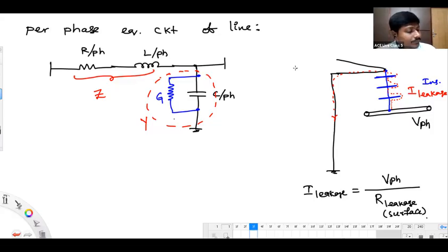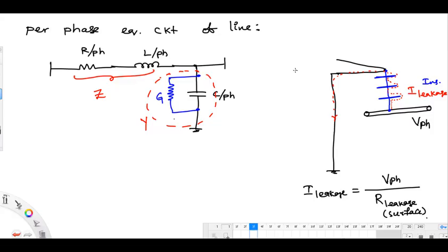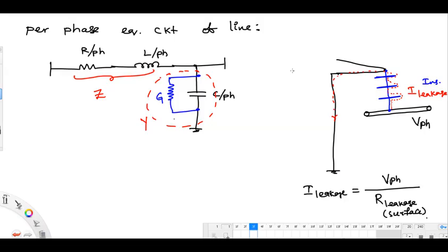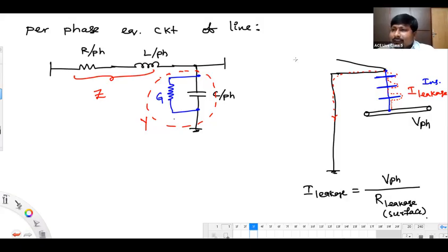One general doubt, sir. Four or five years back, we were using a 60-watt bulb. If we continuously turn it off and on many times, it will fail after some days. Is it due to switching overvoltage, or why is it so? Switching overvoltage will not affect an incandescent bulb at all, because it is a resistor. It gets damaged because of excessive heat and long usage.